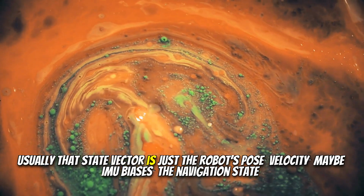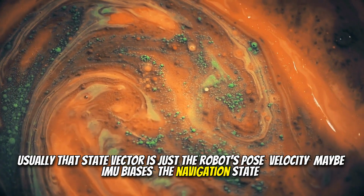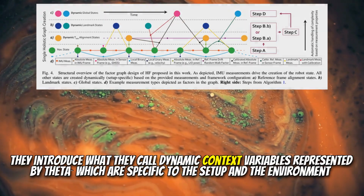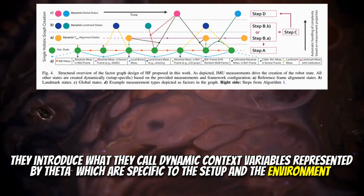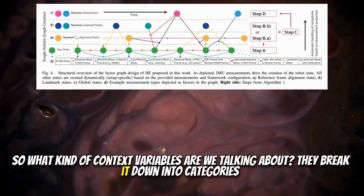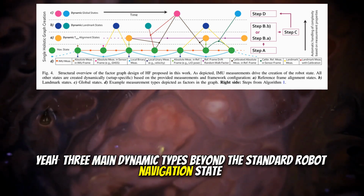Usually that state vector is just the robot's pose, velocity, maybe IMU biases, the navigation state. Right. HF goes way beyond that. They introduce what they call dynamic context variables, represented by theta, which are specific to the setup and the environment. It's not just about the robot anymore. So what kind of context variables are we talking about? They break it down into categories. Yeah, three main dynamic types beyond the standard robot navigation state.